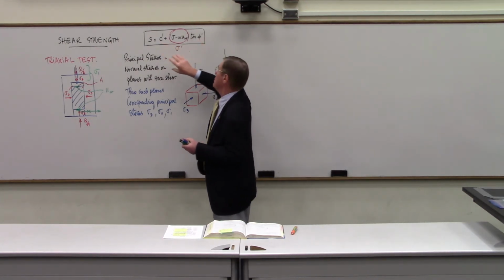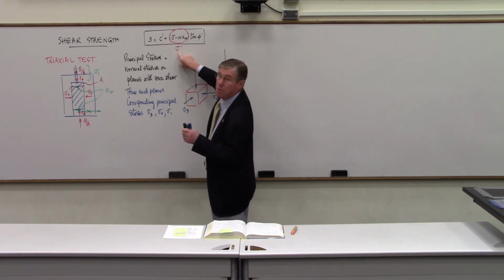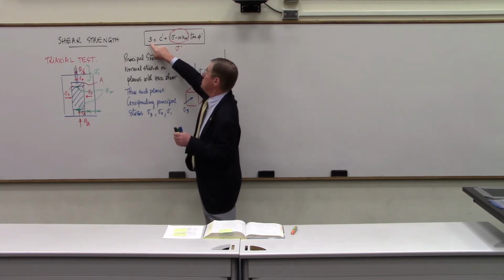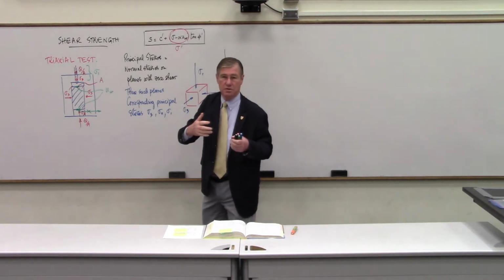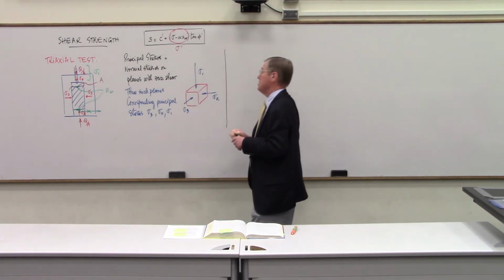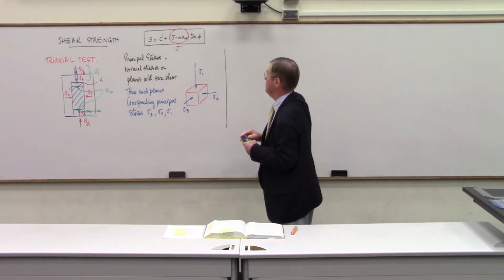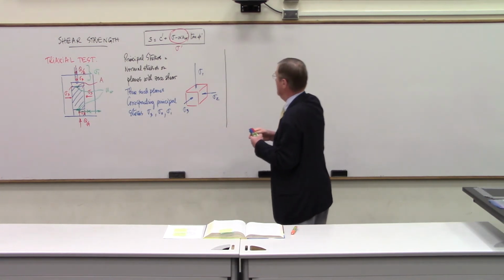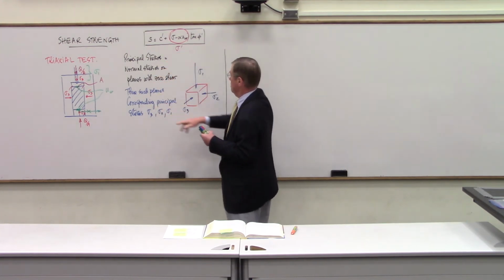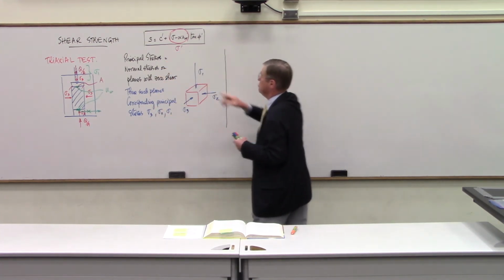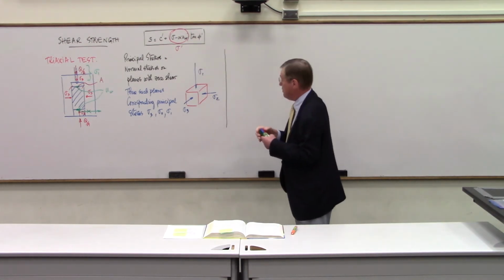If we have those parameters, whatever the problem is, we'll have to calculate this for that particular problem, and then we'll be in a position to find out what the shear strength is, and therefore what is the bearing capacity, what is the earth pressure, all the problems that are associated with these types of parameters and the shear strength of the soil. So the question then comes, how can I use the results of this triaxial test to be able to find the effective stress cohesion and the effective stress friction angle?